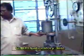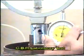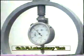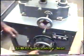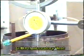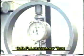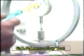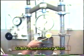The entire assembly is now placed on the compression machine and seating load of 4 kg is applied. The dial attachment for measuring the penetration is set to 0. The load is applied smoothly at the rate of 1.25 mm per minute. The load readings are noted at penetration values of 0, 0.5, 1, 1.5, 2, 2.5, 3, 4, 5, 7.5, 10 and 12.5 mm. The load is released and the entire assembly is removed from the machine.